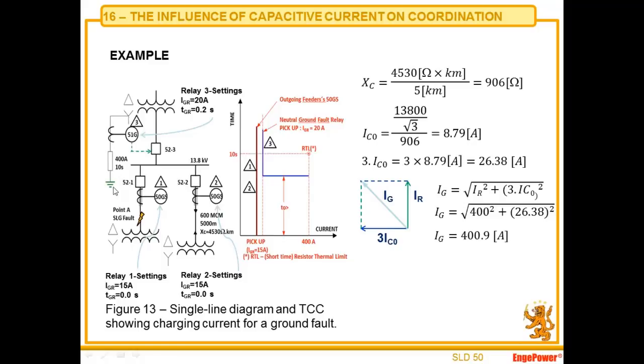If you open the neutral, your system becomes ungrounded. If the system becomes ungrounded, your ground elements will not sense the ground faults. And you may also have transient overvoltage. So when you specify a resistor, ask the manufacturer to provide at least 5% of continuous current relative to the short time current of the resistor.